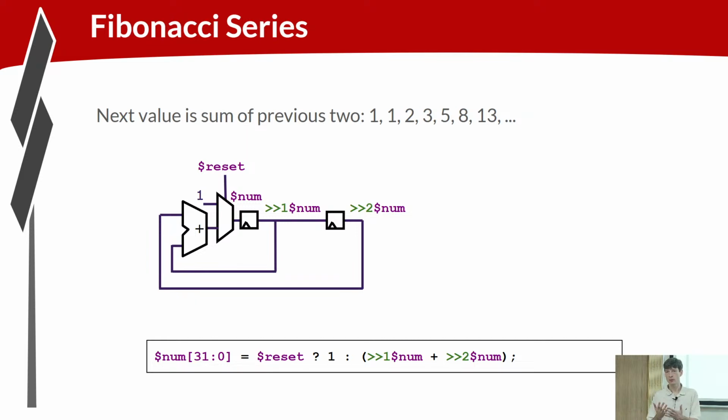If you throw everything into the same pipeline, you could hide what's interesting, that there's stuff happening between operations that are conceptually independent. So for the choice of what logic goes into what pipeline, TL-Verilog is not forcing you into any mode of design, but naturally partitioning the logic results in natural looking code.